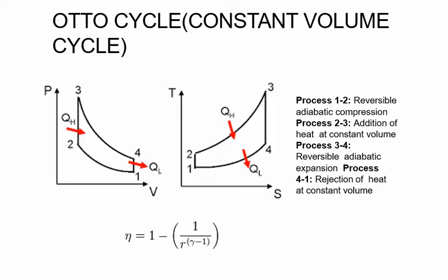The Otto cycle is constructed from, at the top and bottom of the loop, a pair of quasi-parallel isentropic processes, that are frictionless and reversible adiabatic processes. And on the left and right sides of the loop, a pair of parallel isochoric processes that have constant volume.